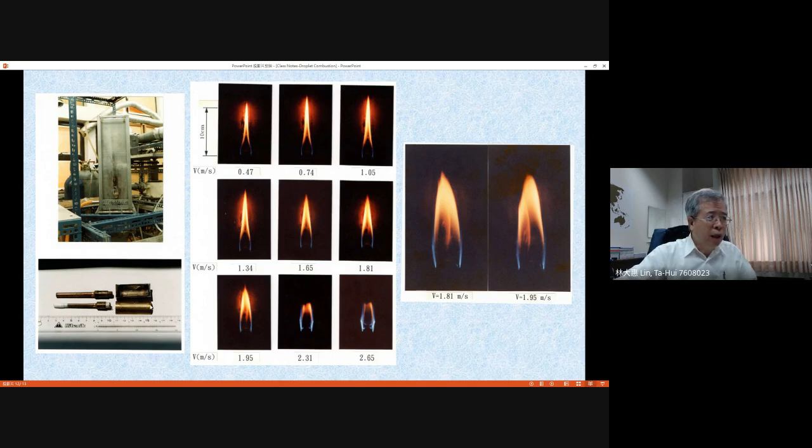There is a slot, and we insert some sponge in it, and for this upper semi cylinder we supply the liquid fuel from the side wall. There is a tube connected into this semi solid cylinder, and the liquid flow will move to the slit, go through the sponge and overflow from the surface of the cylinder.